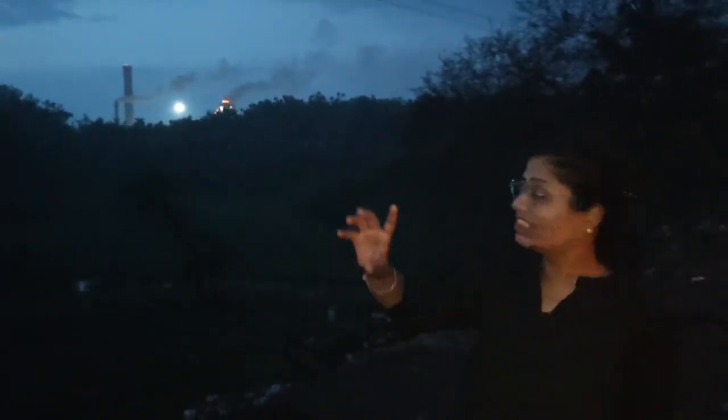So guys, I'm standing slightly away from a factory outlet. Actually, I wanted to show you the type of plume. If you can check it out there, zoom it once. So you can see there, a Coning Plume is there. Right now, the wind velocity where I'm standing is greater than 32 km per hour. So the type of plume which is being liberated, just check it out there.